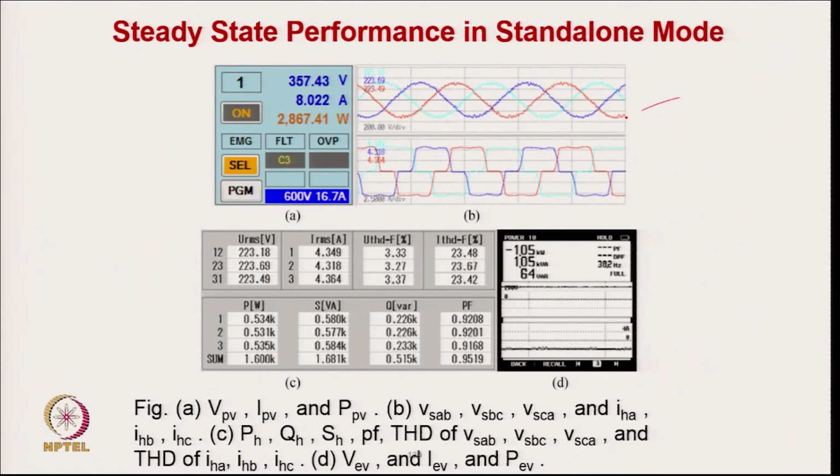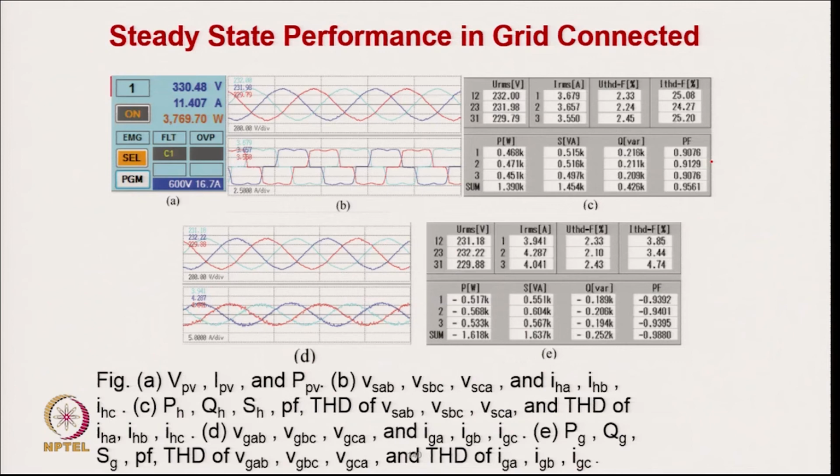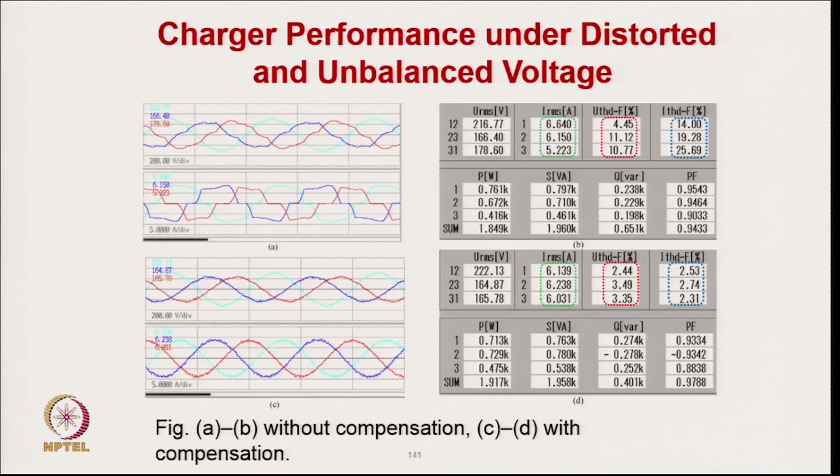So, you can see the THD of the voltage is quite low, in spite of feeding a non-linear load. But the grid current remains sinusoidal when it is connected to the grid. So, the grid is not affected, as this voltage source converter is providing the harmonic filtering here.